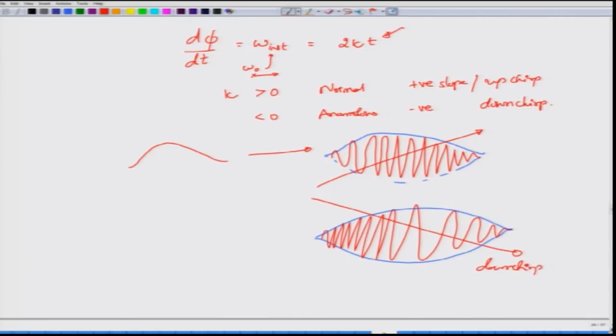So, the effect of dispersion onto the pulse that is propagating, which is initially unchirped and Gaussian, is to actually retain the Gaussian character, and in the absence of losses have the same energy as the input, but this pulse at the output would have broadened out mostly, and it would have also acquired chirp. Okay. So, this effect is not desirable, and mitigating this effect occupies a lot of interest in fiber optic communication system design, something that we are going to see in the future modules. Thank you very much.